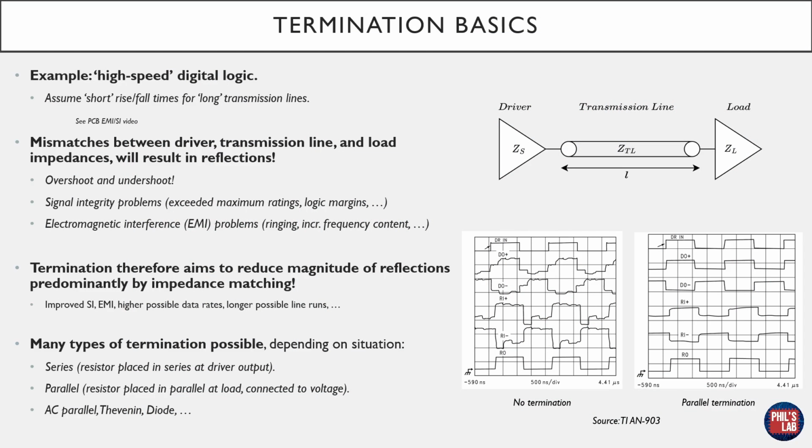Before we start looking at parallel termination, let's go over what termination is and why we need it. Termination exists in various different signaling, for example RF and digital. In this video, I will be focusing on high-speed digital logic. High-speed digital logic I've put here in quotes because high-speed is a very hand-wavy term. Effectively, high-speed typically means short rise and fall times, so fast edge rates, and comparatively long transmission lines.